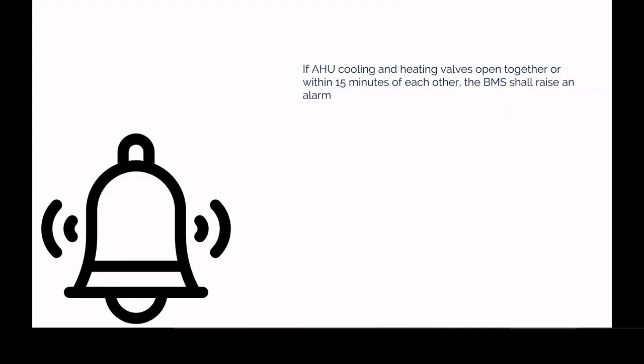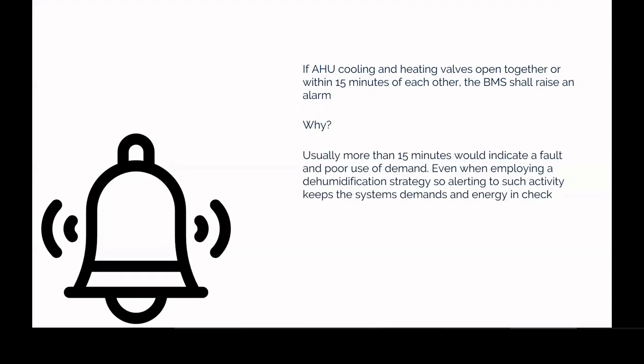If AHU cooling and heating valves are open together or within 15 minutes of each other, the BMS shall raise an alarm. Why? Usually, more than 15 minutes would indicate a fault and a poor use of demand. Even when you think about things like dehumidification, anything over 15 minutes is probably not right. It's probably more at play there than a controlling element alone.